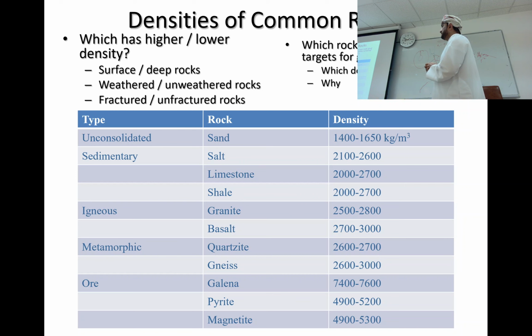So usually when we do gravity measurements, the final objective, as I said, is to measure the variation, the difference from one point to another point. What is the difference in little g, small g, from one point, not the absolute value. I will say why we don't measure the absolute value very soon. But in general, we measure only the small g, which is due to variation from one point to another. That's the measurement we do in gravity surveying.